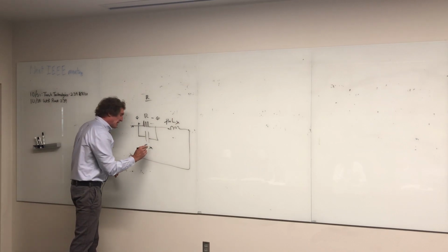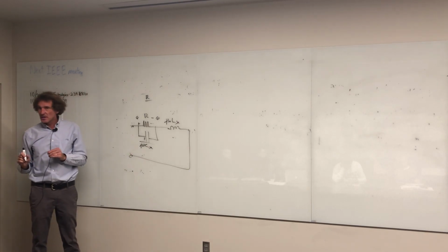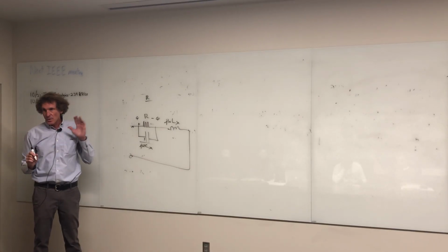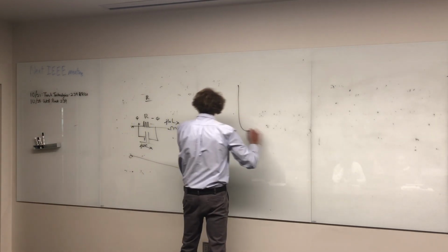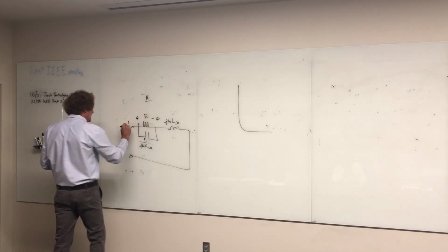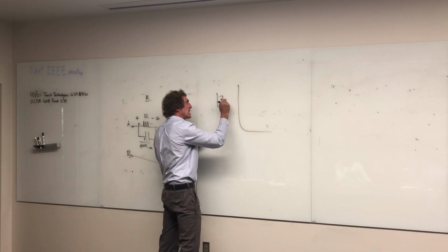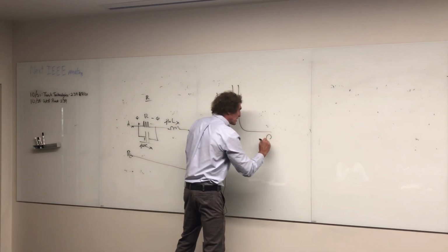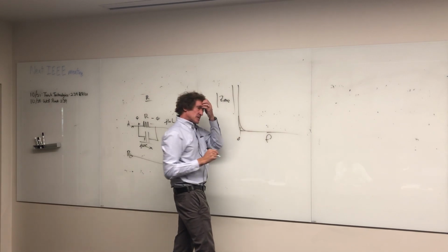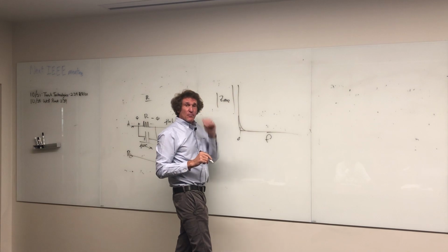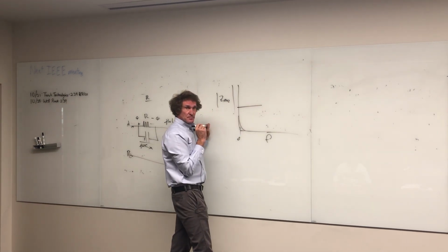Now, you know the impedance of the inductance is j omega L, right? And the impedance of the capacitor is 1 over j omega C. Now just listen to me. I'm only going to do this once. You're electrical engineers, you're very good at what you do. If I looked at the resistance between terminal A and terminal B, and I wanted to plot the magnitude of impedance between A and B against frequency, logarithmically, at 1 hertz it looks like a resistor.